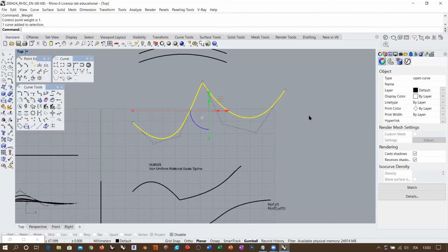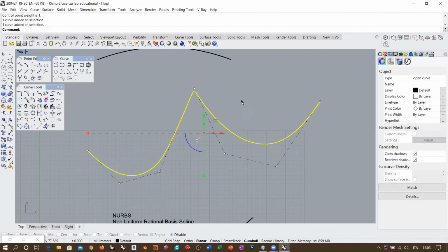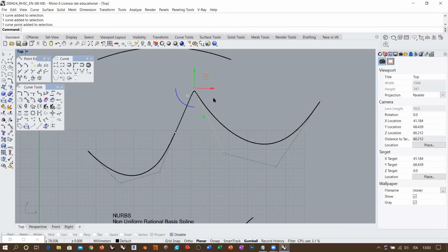But remember that this is a possibility that you can consider when creating your design. Because as you can see, one thing that eventually you might want to do, instead of increasing the amount of control points to deform the shape of the curve in a particular spot, is to increase the weight of the control point that lies in that area in order to pull the curve stronger and create some kind of, let's say, more sharp behavior, right?